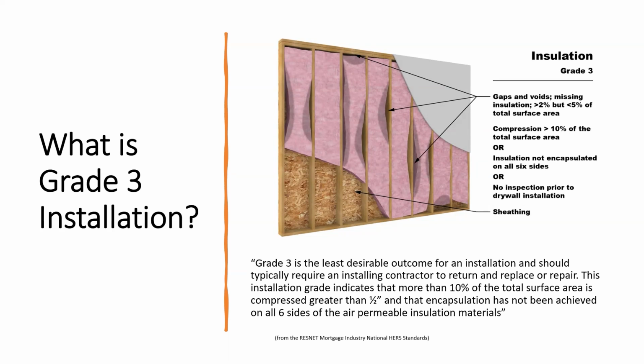So you're missing stuff. We always called out and red tagged for, hey, you don't have an air barrier underneath the tub. Well, yes, that's code required. But if I just said, okay, fine, if you want to leave it that way, I'll just do it as grade 3. Well, someone now needs to go inside the energy model and list it as a grade 3, or list the home as overall less than grade 1, and see if it determines whether it passes or fails the model. If it doesn't, it really should be red tagged and not allowed to go forward until it's corrected. But a lot of times we don't have real time energy modeling updates or recalculating to make sure that it's passing.